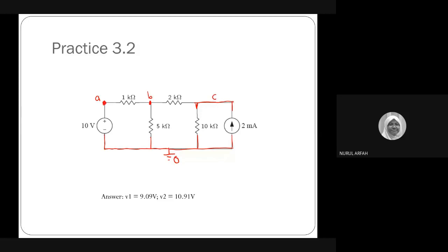Just by looking, can you identify the value for A? 10, madam. Right, 10. How do you know? Because this is a plus sign. A is the higher polarity, minus the lower polarity, which is the ground, and then equal to the value, 10. So A should be 10. So just remove this and replace with 10 volt.